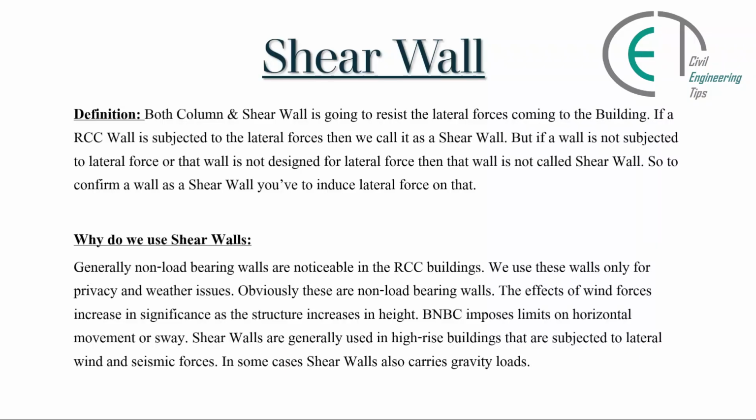Let's first discuss the definition of shear wall. Both column and shear wall are going to resist the lateral forces coming to the building. If an RCC wall is subjected to the lateral forces, then we call it a shear wall. But if a shear wall is not subjected to lateral force, or that wall is not designed for lateral force, then that wall is not called a shear wall. So to confirm a wall as a shear wall, you have to induce lateral force on that.